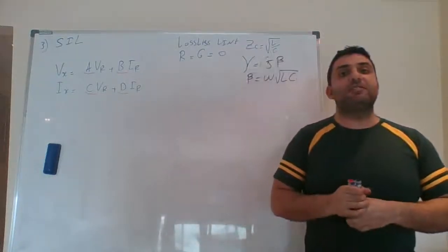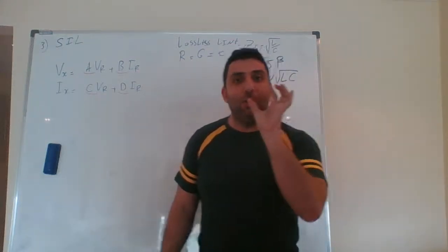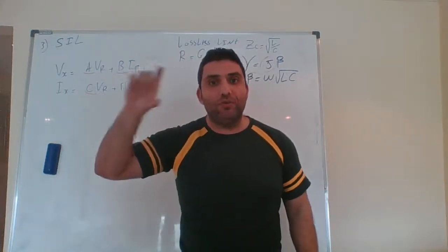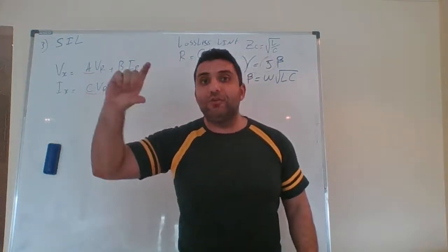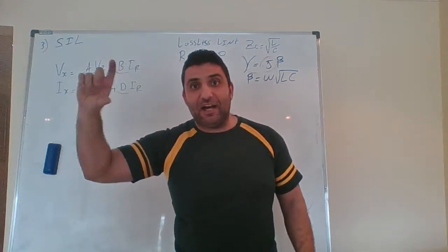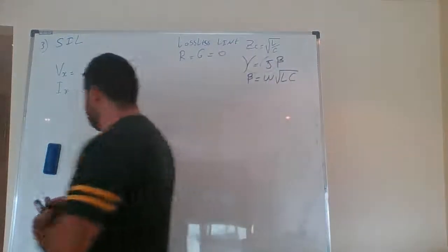What's a surge impedance loading? The surge impedance loading happens when I have a resistive load connected across the VR that has the same magnitude as the surge impedance.